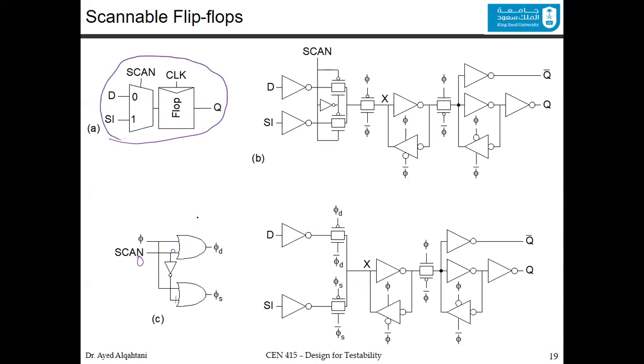And by only adding this multiplexer, whichever way you want to choose, you can make testing sequential circuits very easy. For the combinational circuit, we gave you an example, and we found out how to find the test vectors, and there are even tools that can help you with this. But for the sequential circuit, we only have to add this simple multiplexer.